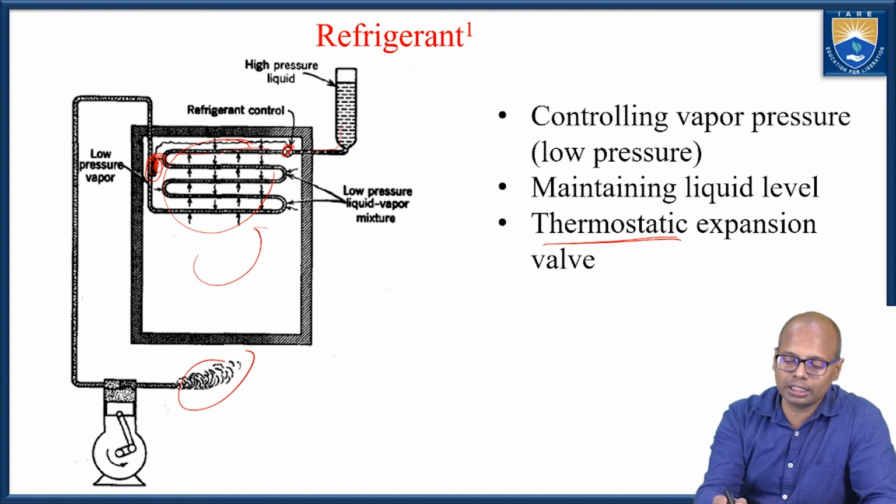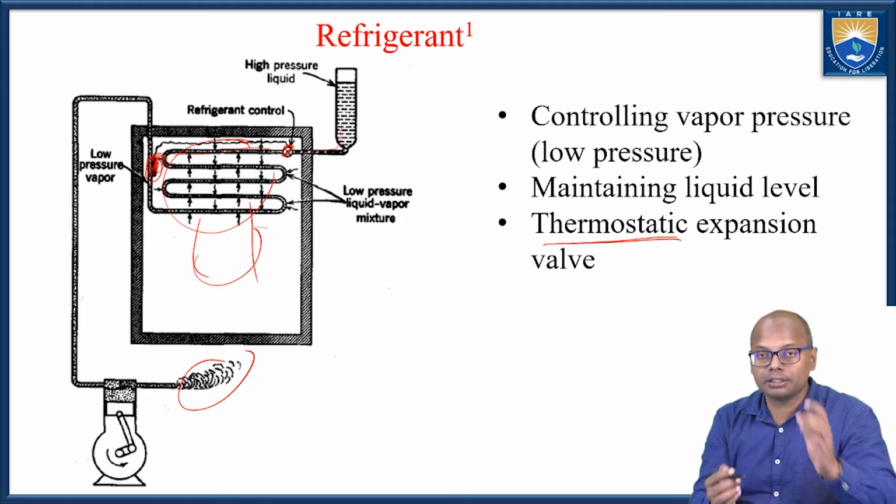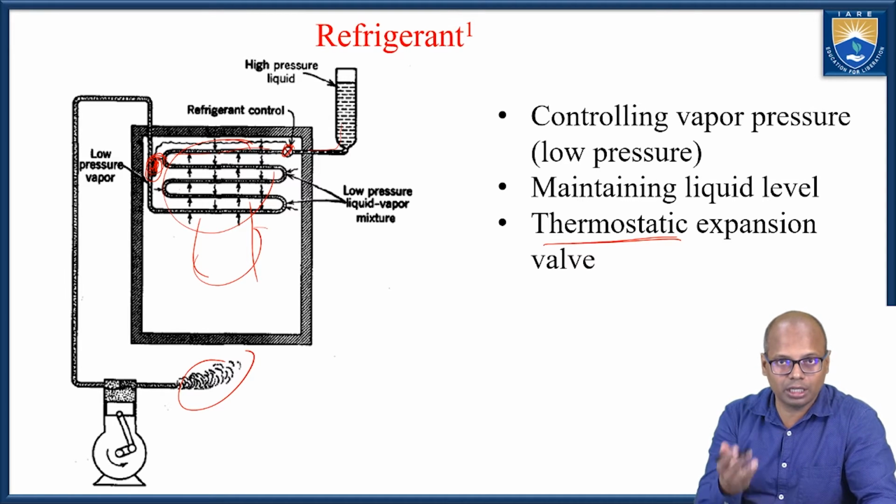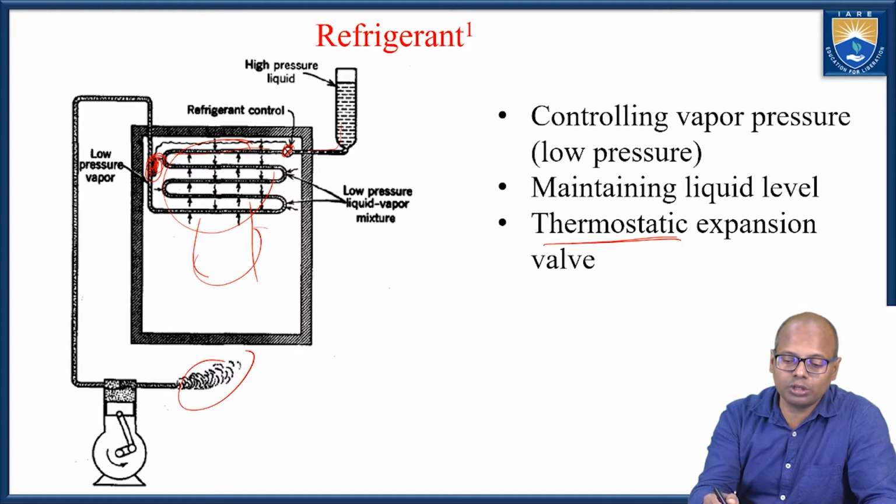It will flow as liquid, take heat from this refrigeration space and start boiling, and finally it will be vapor at this space. When the temperature at this point reaches the boiling point of the fluid and it evaporates, then this valve will be opened.